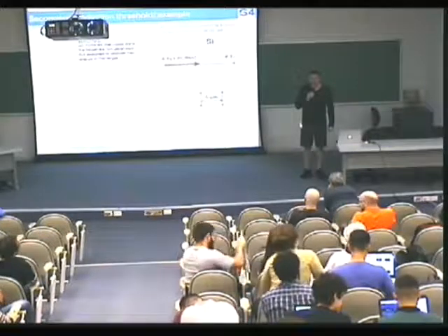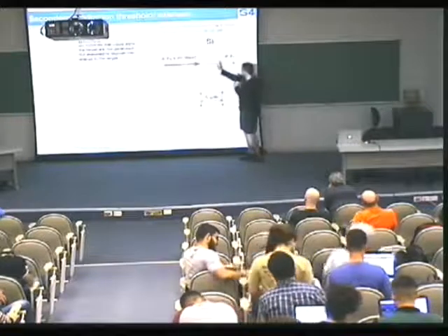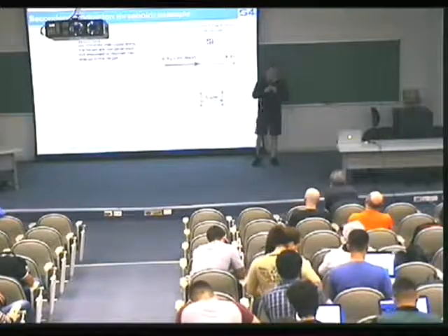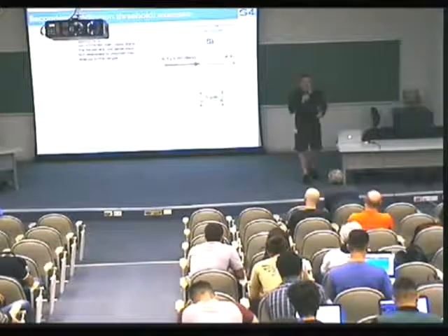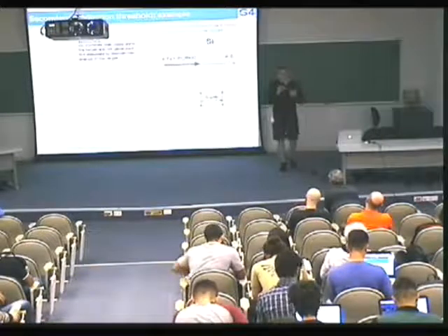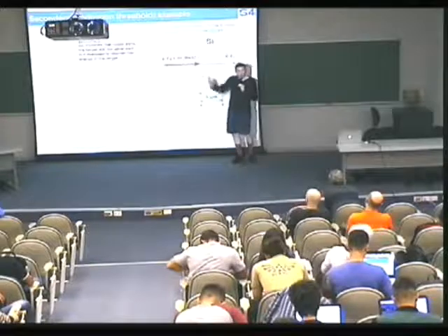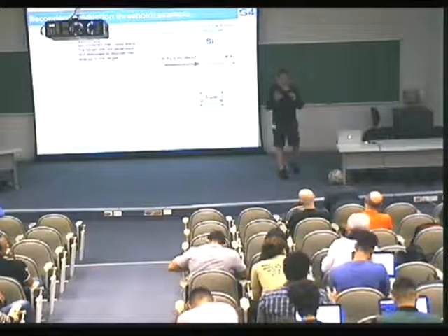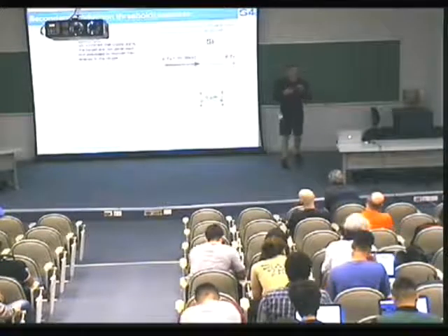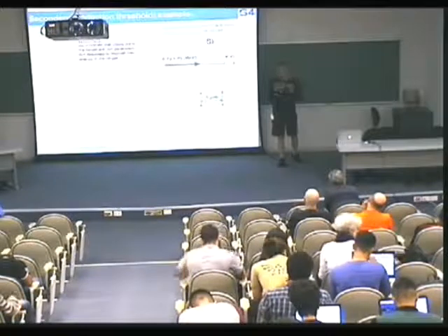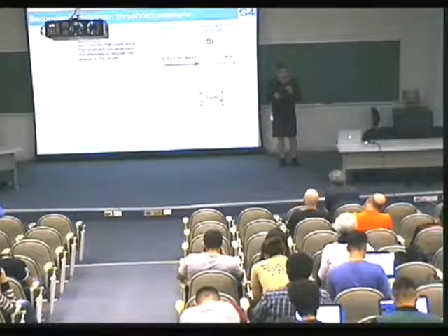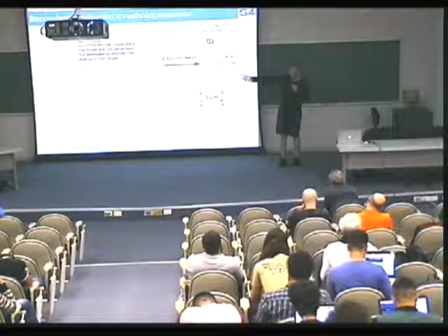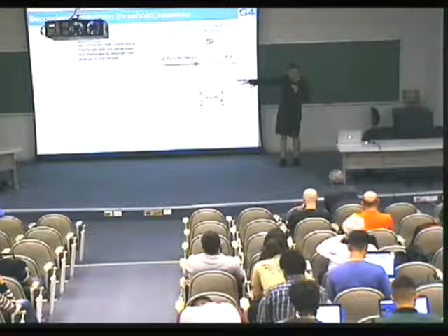Yeah, but you mean that here I emit photons and here I don't emit photons? I didn't go into these details, but there is a command to do this. Because if you go closer and closer to the boundary, you want to emit photons to lower and lower energies, okay, because it can go. And there is a command to do this, actually. By default, it's not there because of many reasons, but it's possible. That will give you the full correct behavior. But as you can see from this example, here it doesn't change too much. 5 micron is still fine, gives a proper result.